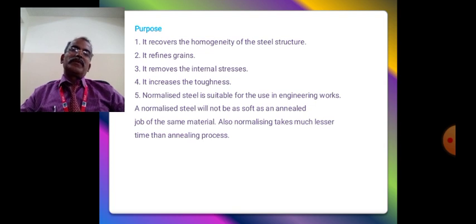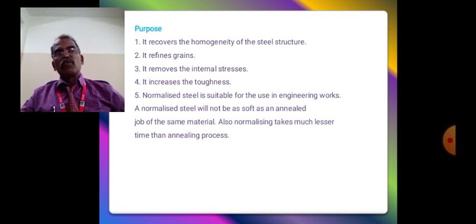The purpose of normalizing: during normalizing it recovers homogeneity, so the structure is homogeneous throughout the solid. It refines grain, removes internal stresses, and increases toughness.